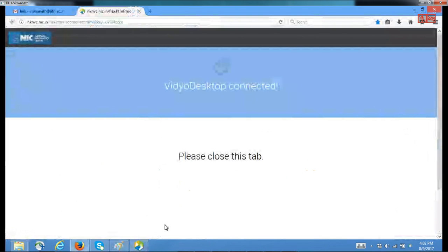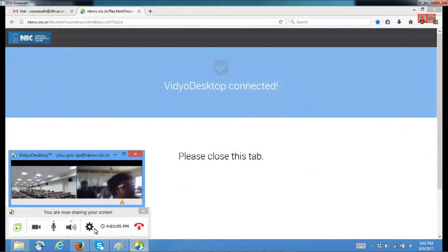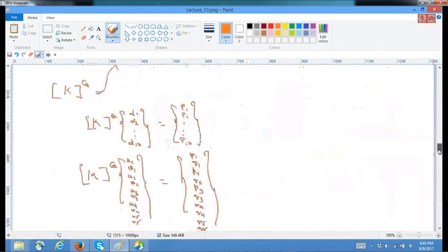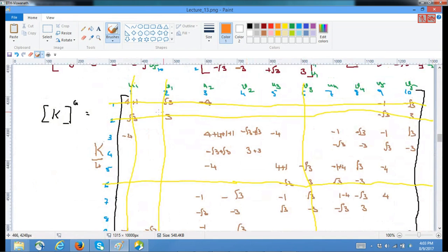So this is the second question people are having. I'm glad that people have asked me this problem. If you have an element that connects U1 V1 and U3 V3, there are two elements that may connect it, but not directly. That means they are unaffected. For U1 V1, U3 V3, if nothing is there, you need to take a zero value. So here I didn't write it, but you need to take all these entries as zero. Wherever I didn't make any entries, these values are zeros.